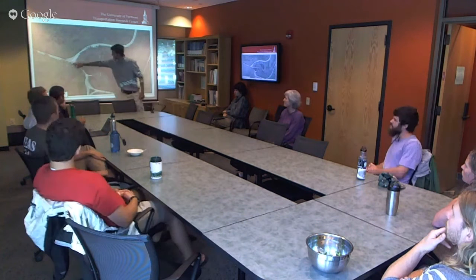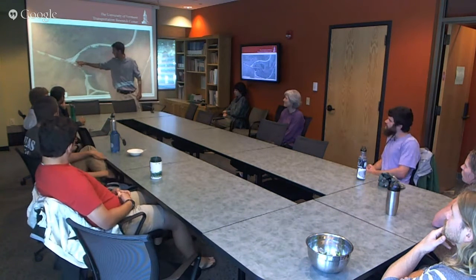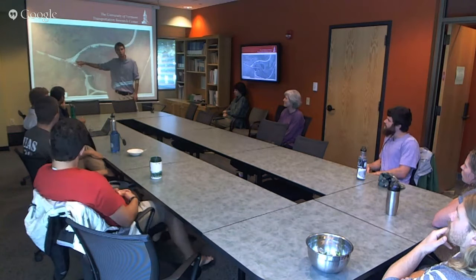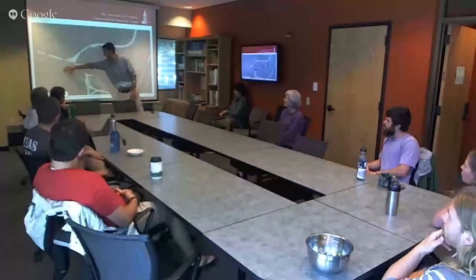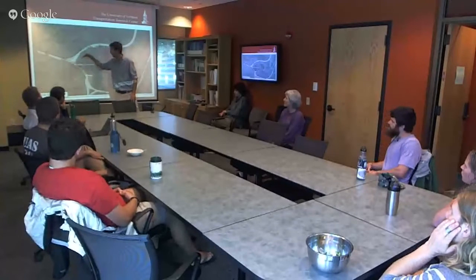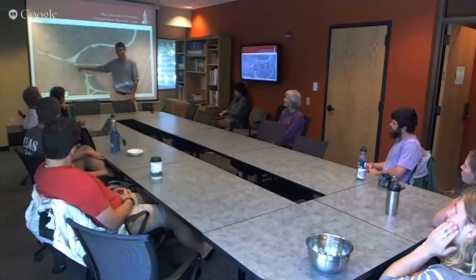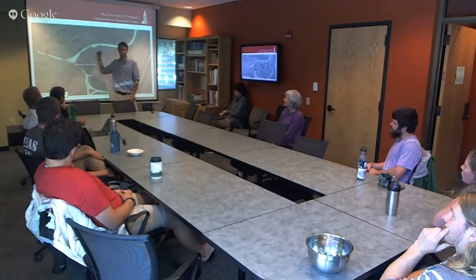If you look here, we would have put it right about there, because if you look at the place itself, you see that the river kind of wants to go this way. There's a natural floodplain here, and the river keeps on going this way. So this is the abutment that's having a lot of issues because the water is slamming right into it, which is a big issue.